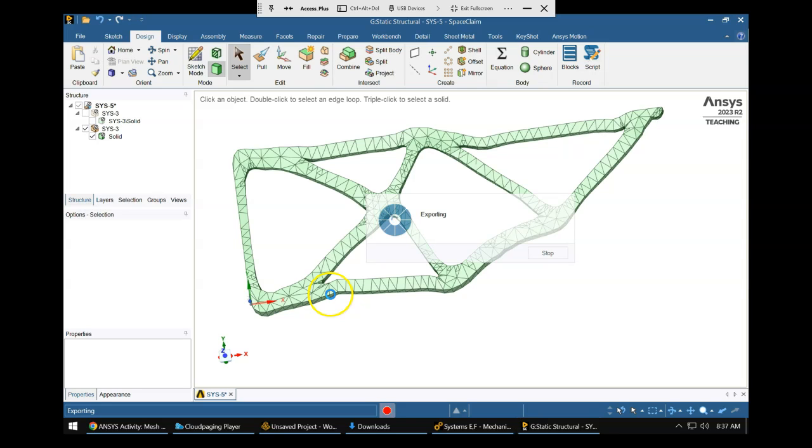So if I wanted to go in SolidWorks and make a cleaner design out of this, that's one option to go from that SpaceClaim, that morphed, and this works in topology optimization as well. Take that morphed or topology optimization result, go into SpaceClaim, turn it into a solid just by right-clicking it. I think you have to do that step for it to work as a step file. Then you save as step file. Then you can open this in SolidWorks. If we got time at the end, I'll show you what that looks like. But so now we're done here.